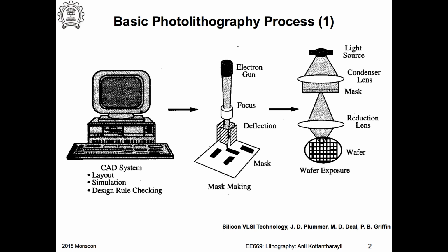I've designed this maybe even in PowerPoint, because we are talking about fairly large features, 0.1 mm. I lay out these features and get them printed on a transparency. I can use it in a photolithography system, because the transparency is transparent and you are printing black ink in regions where you want to block the light. So you have a very simple mask.